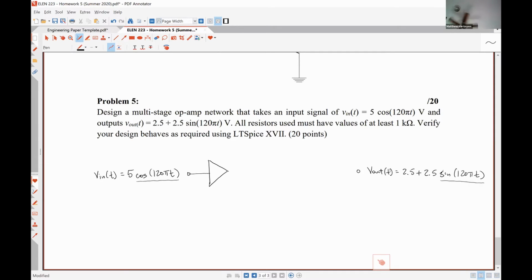The reason that I'm going to use a differentiator is because the integration operation in circuits usually has some sort of initial condition that I need to pay attention to, and I don't want to have to deal with that because that would effectively require me adding also a switching circuit, which is going to be potentially annoying to implement. So my first stage is going to be a differentiator.